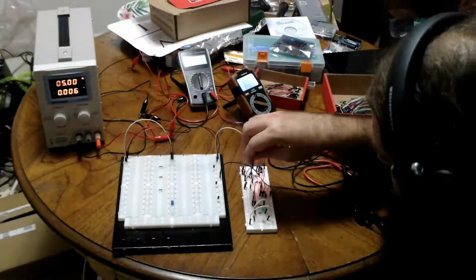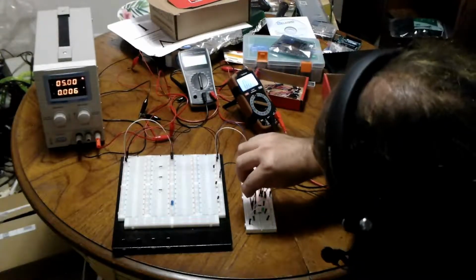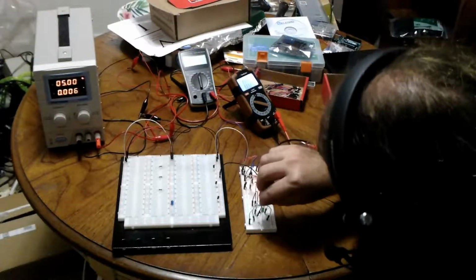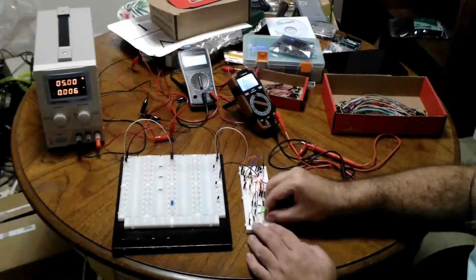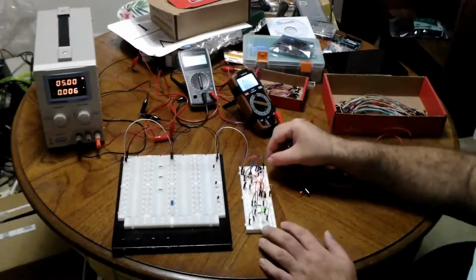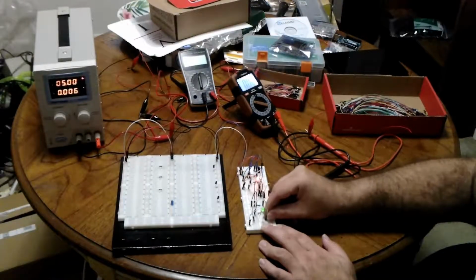So we have a voltage there. Coming out of the switch is fine, there is fine, there is fine, there is fine, but at the start of the LED, that is fine. Aha! So in this case, it was not a bad wire, it's a loose wire. So there we go. Now we have our red LED, and we have our green LED. Now I'll put this in a different hole, try to make it a little less wiggly.